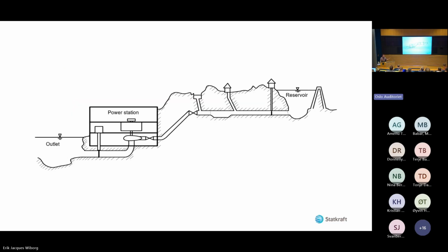So, just a quick recap of how a hydropower plant works. We have a dam that will keep the water from flowing away. We will have a trash rack that is kind of the coffee filter of the power plant. You'll have a gate system, which is very useful if you don't want all the water rushing into the power plant when you're doing work there.